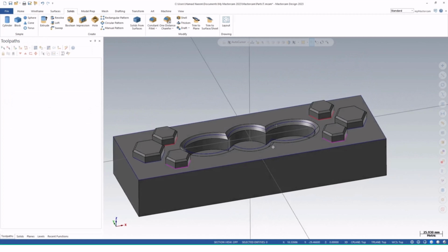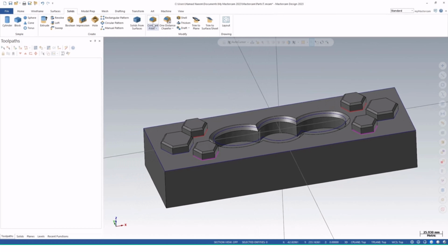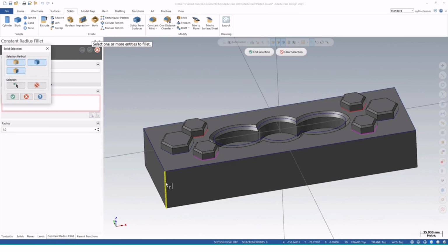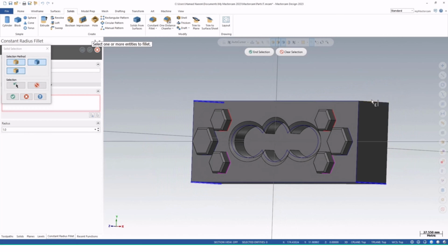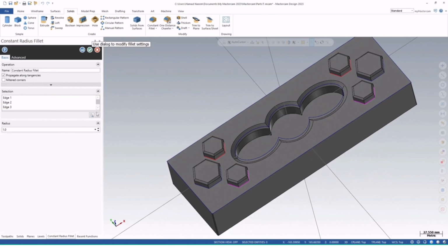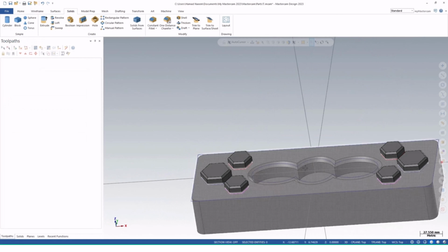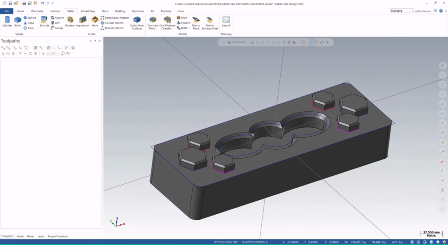So that's it. And some rounds on this. Let me select fillets here, and this point, fillet. How about 5 millimeter, 10 millimeter? Let me make it 10 millimeter fillet around this. So this is how we create the geometry.